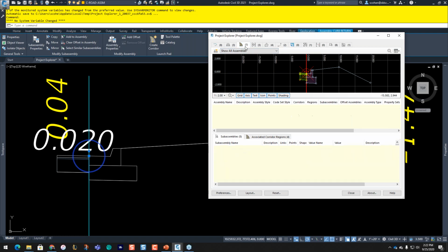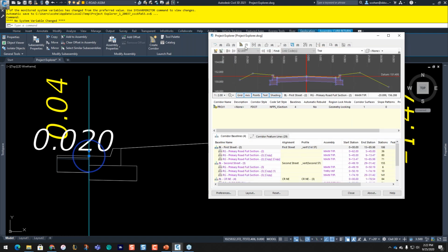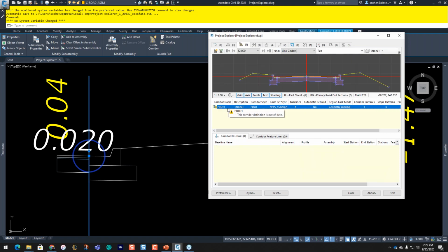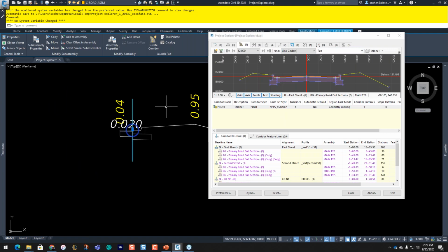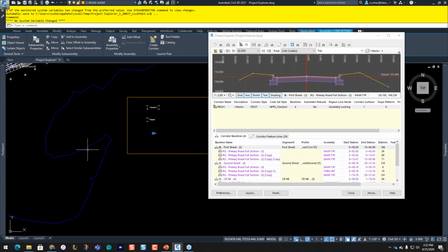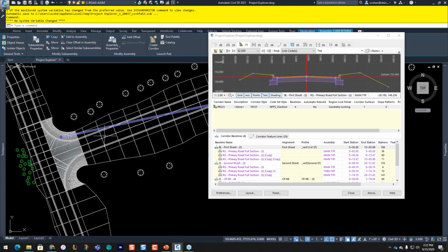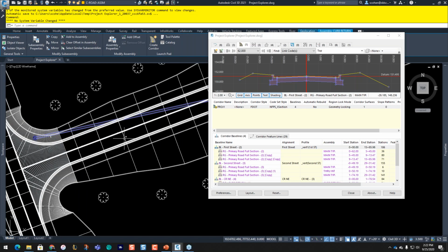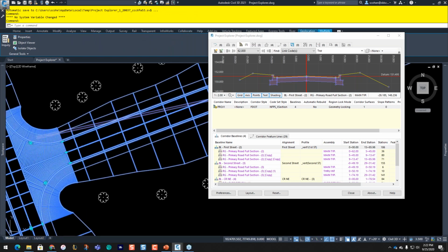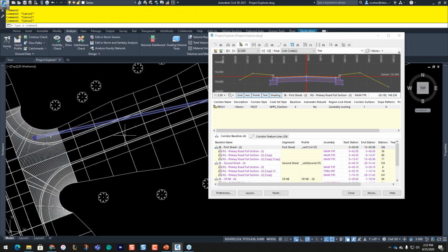All right. Now, the corridor option is quite possibly the best option ever. It really is. This here is just fantastic. For those of you that have done corridor modeling, what's the key thing that you do to edit a corridor? You zoom in here, and to see it in cross-section view, you would select it at the station you want to look at. Oops, I got more than one thing selected. We'll just go ahead and select it here, and then go to the section editor.